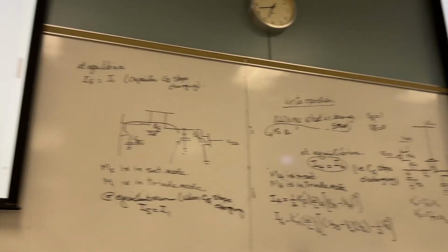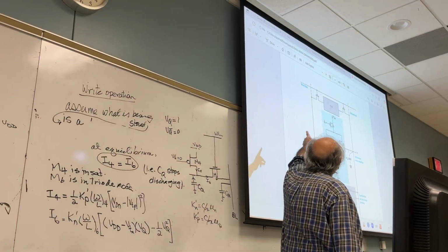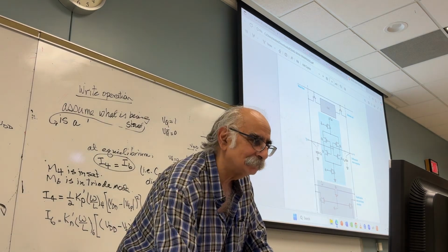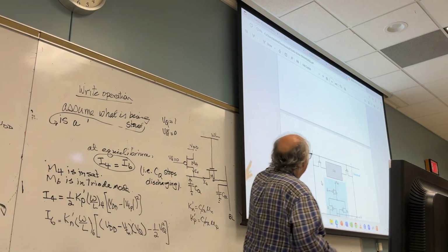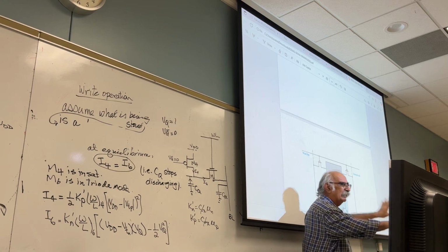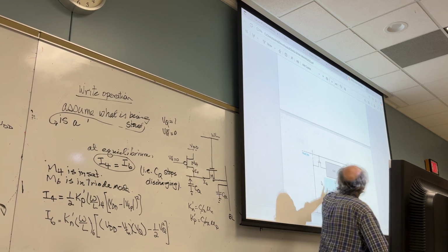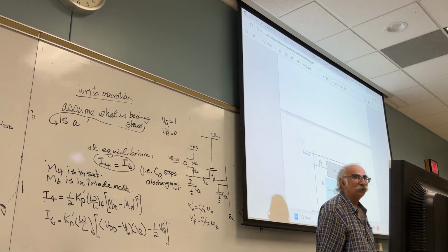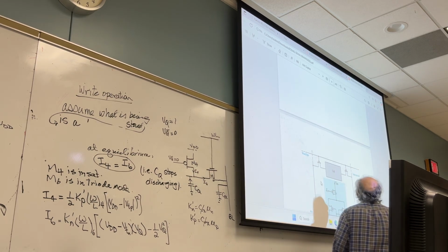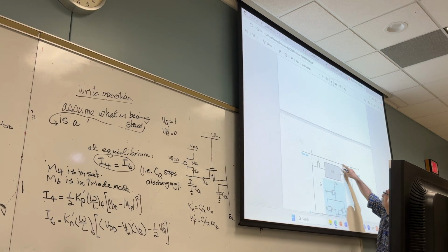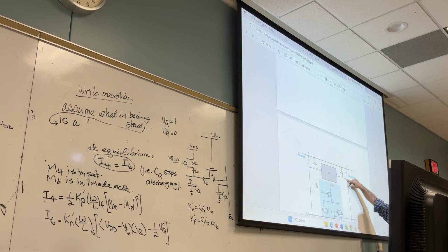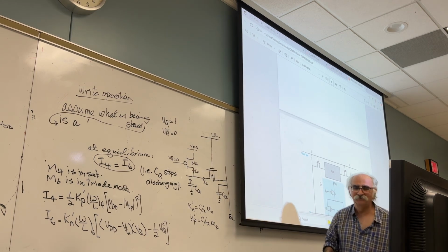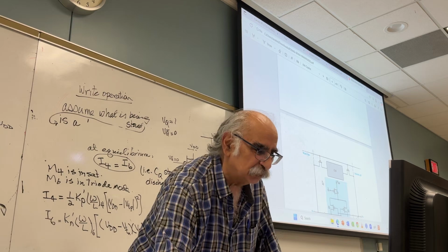But let me look at the part. Do you see the top? The top. This one? What is this one? That's the SRAM cell. What goes inside the box? The back-to-back inverter. Did you get it? Good. What is this? That's the word line. What is this? The bit line and the what? Bit line bar. I want to show you, first of all, the pre-charge.